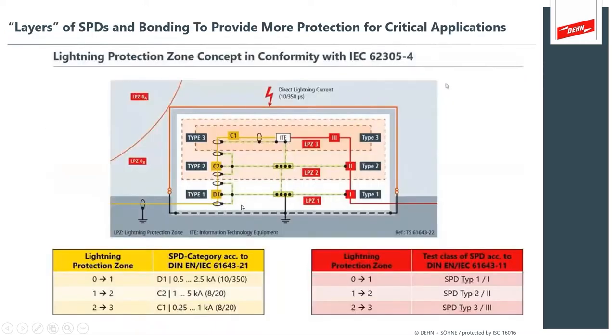So this all contributes to what we would call layers of protection, and to create a zone of maximum protection. So you have something like your most exposed point of your AC power distribution coming in, and then as it goes downstream into your electrical system, you can build more and more thorough zones of protection. And this is what we can look at at a block diagram level, and then you can inspect your site and see that it was actually implemented correctly.